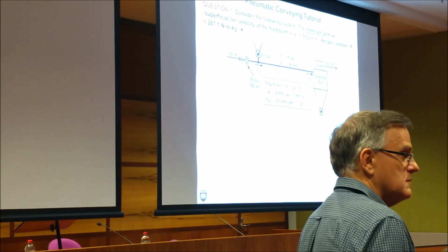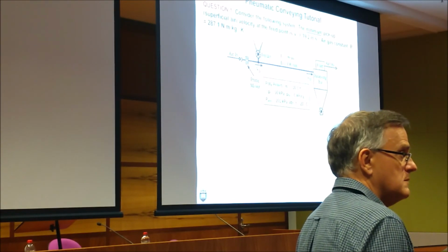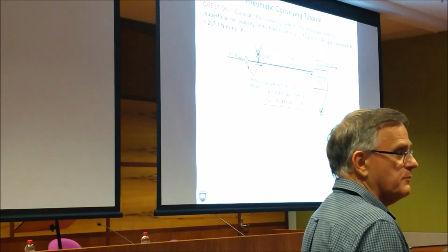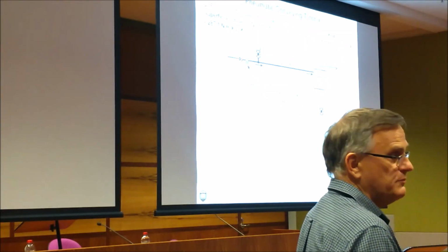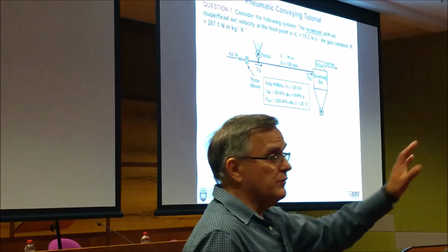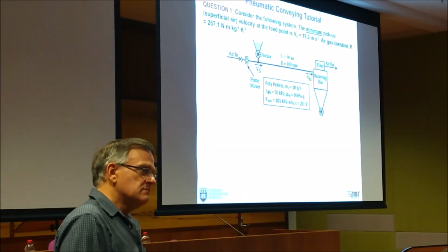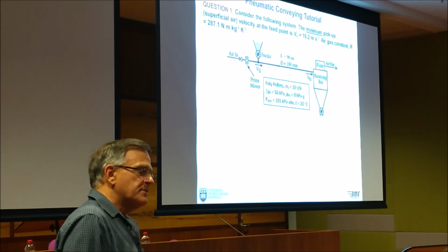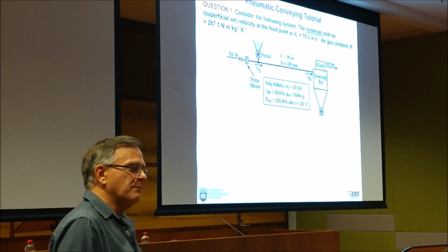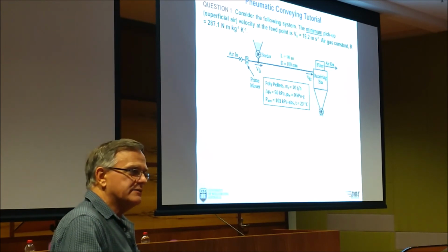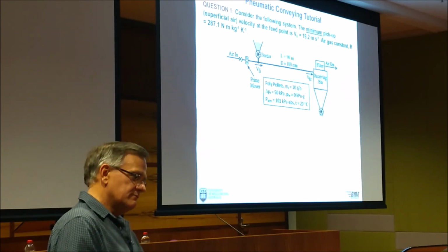Do you have any method for monitoring this before failure, or just wait until it happens? Just wait until it happens, and then you've got a problem. But usually if you've got a toxic mixture you can't wait, so you've got to do NDT testing, thickness. You have to go around and check your bends, which sometimes is necessary. But generally most people don't care until it's a problem, and then it's too late. It starts going on, and then you get the duct tape out and the elastic.